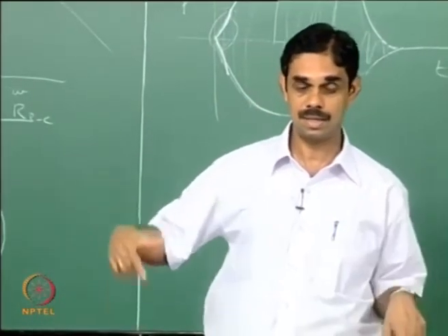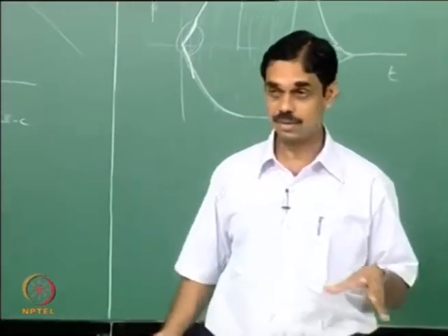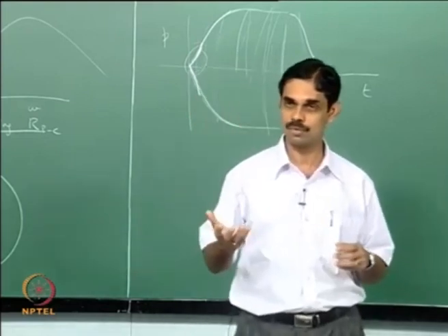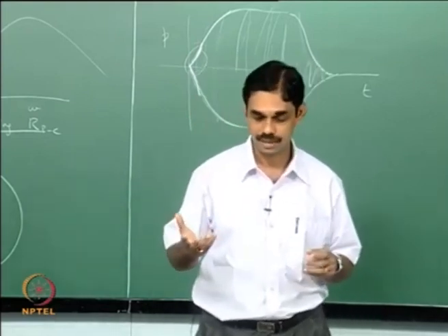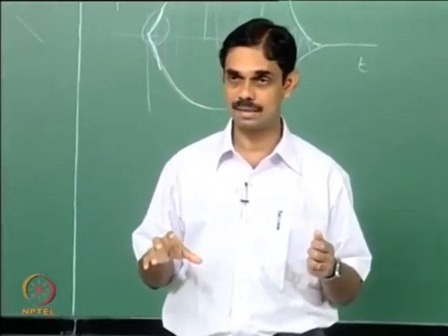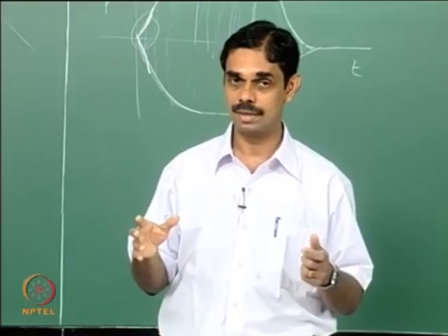So this can oscillate, and this particularly happens when your volume is less. So L star would mean, do you remember what is L star? A characteristic length is volume divided by throat area. So when you have low L star, that means low volume, you have this instability.